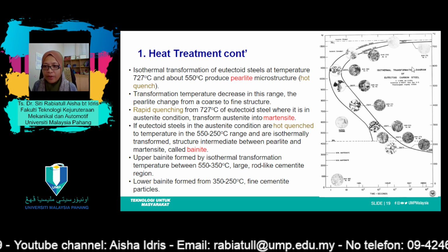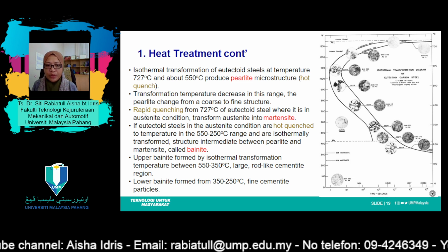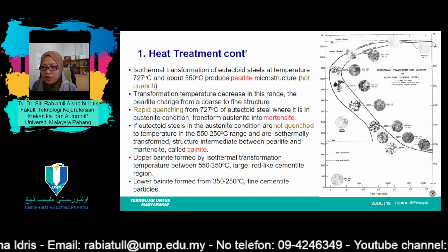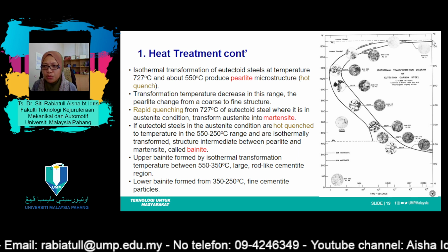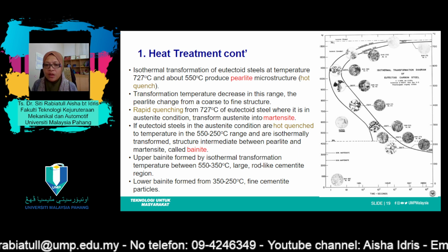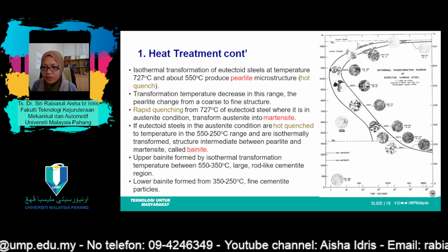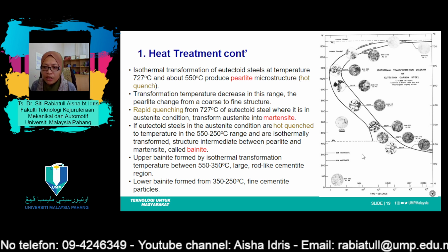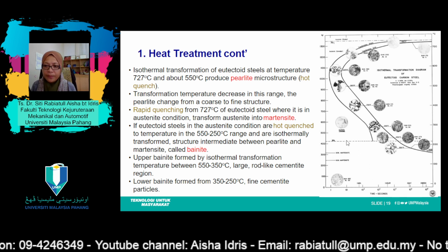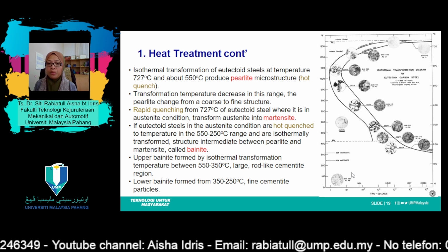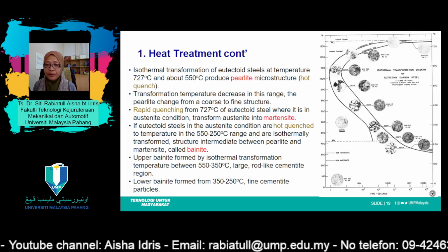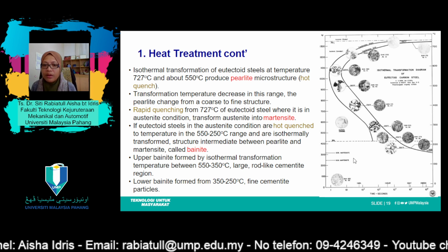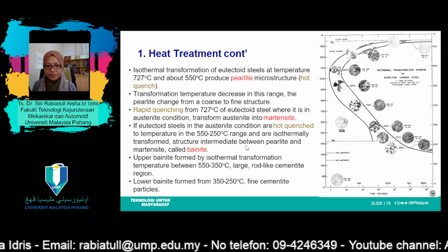Okay, so in this same area, number 3 is rapid quenching. From rapid quenching, from this case point, it will turn into 100% martensite over here. Later on, you will see the lines for 50% martensite and 100% martensite. So rapid cooling, starting from this point, reaches martensite.